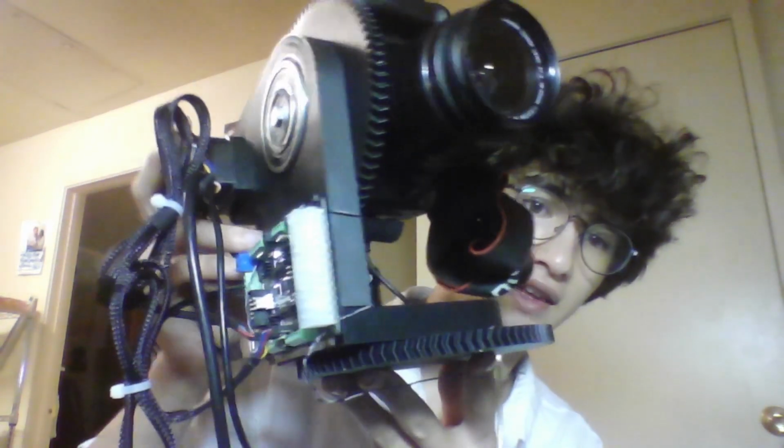Surprisingly, torque wasn't an issue on the motors as long as the accelerations were set to relatively sane values, which I discovered. Otherwise, I was skipping steps. But yeah, that's pretty much the basics of the mechanical design. It's got this stage that rotates on the bottom gear, and the motor here is static, and then it engages with that gear and rotates that one.